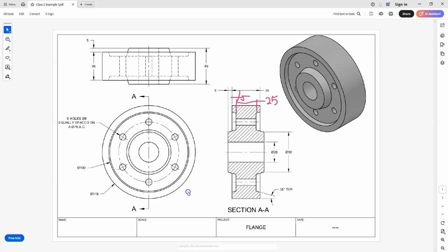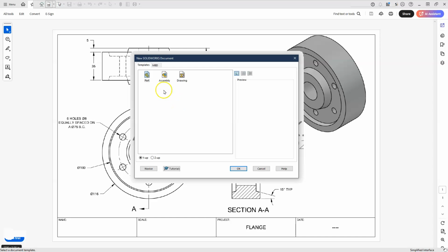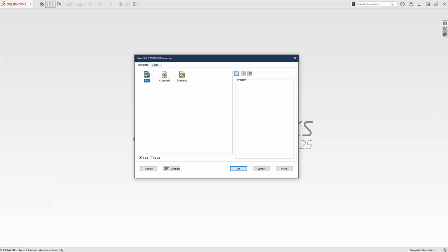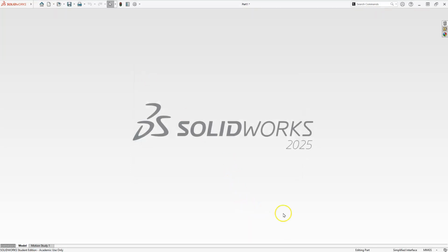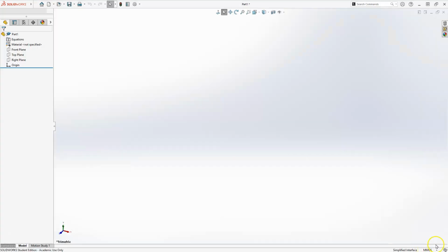Here in SolidWorks, I'm just going to start off by clicking the new icon, and then we're going to double click on here where we're going to create a part. Now I will be creating this part in millimeters, so I will make sure I bring your attention to that once SolidWorks is up and loading, but you can already see it. It's happening right down here in the bottom corner. That MMGS, remember that stands for millimeters, grams, and seconds. Okay? And here in a second, I'm just waiting on that ribbon to come across the top.